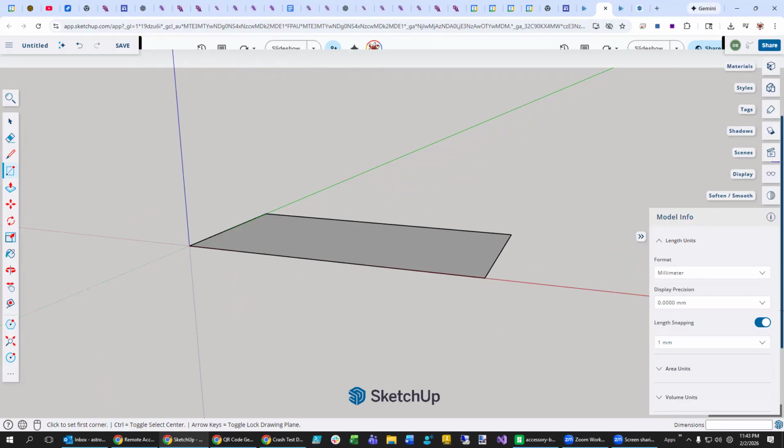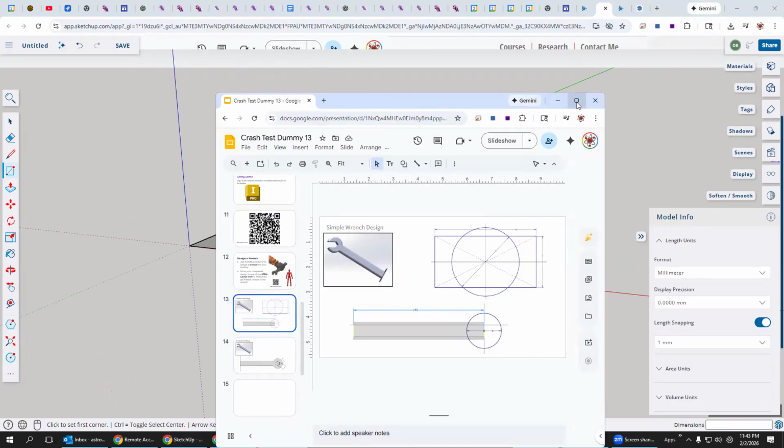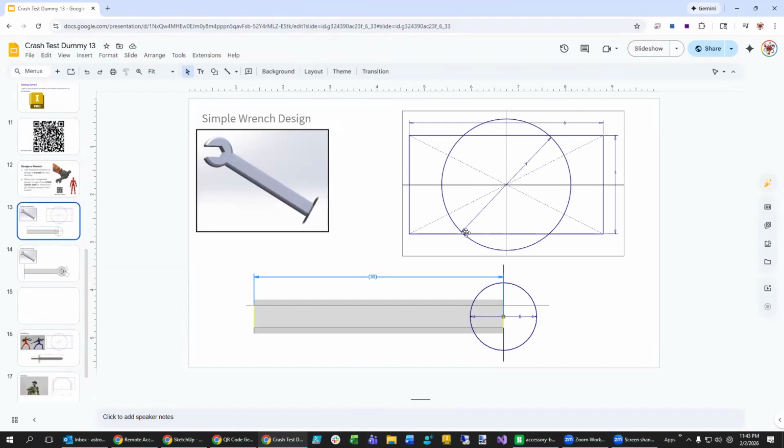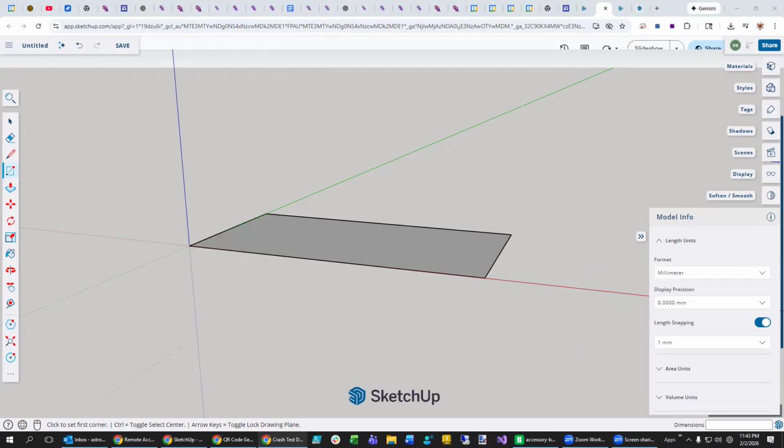Now, the other thing that we need here is to have that circle in the middle. And you see that the circle has a diameter of 4, but SketchUp works in radius instead, so we're going to need to type in 2. Let's see if we can find a way to get this pretty close to the center. Maybe when we hover over this edge, can we find the word? Oh, there's the center. And can we find the midpoint going the other way, like right here? There's the midpoint. So I guess somewhere around here in the center is where we want to be.